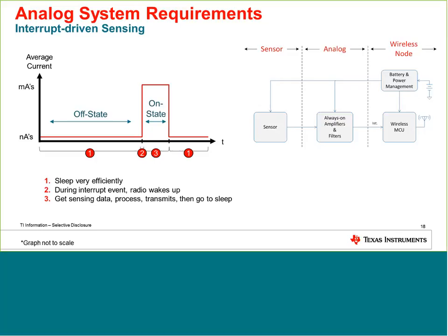So now if someone enters a room, what will happen? The sensor will detect that and will send an interrupt and will wake up the microcontroller. So here I'm showing two different approaches. Sometimes when you need to have a sensor always on, the power requirements are much more stringent compared to the applications when we are just measuring on a regular time base.